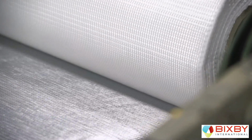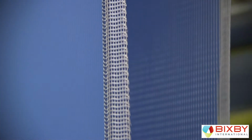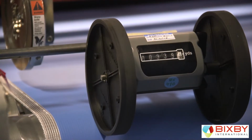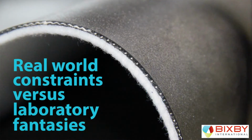And as important is making sure the adhesives or the tie layers you're going to use to make that laminate function as a whole, the choice of those adhesives needs to match the properties and the functionality of each layer to be successful. Therefore, each component layer and their chemistries and the adhesives and tie layers used need to be optimized from a number of vendors. All of those variables in tie layers and functional layers makes a very simple process much more complicated. So it makes a lot of sense to bring all of those specification and engineering requirements, making all those decisions under one roof, managing all of those relationships.